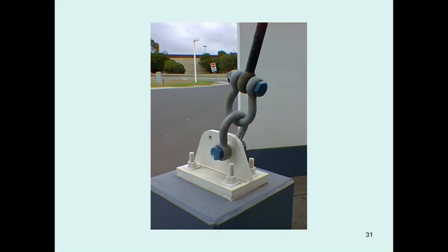Let us consider a bolt. This bolt is subjected to a force that is applied to it, and the bolt will resist that force through the connector here. If we draw the free body diagram of the bolt, we will have the applied force here, and we will also have the resistant force here. If this is F, this is going to be F over 2, and this is going to be F over 2.